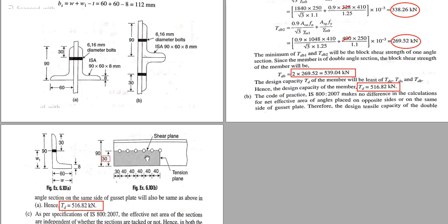It may be required that, to maintain the pitch, there is a minimum pitch and maximum pitch, so some bolts may be required to maintain that criteria. Those bolts will not provide any strength and will not be considered in calculating the strength, so that is tag bolting. It is not our concern about the tag bolting.